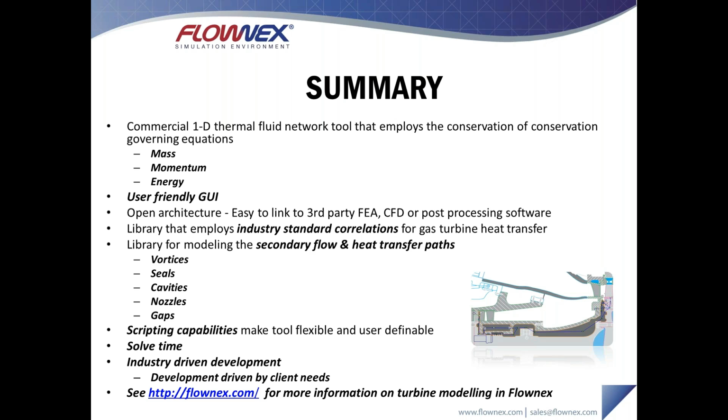The software itself has scripting capabilities to allow users to input custom correlations. So if you have in-house correlations that are not publicly available, these correlations can quite easily be included in your model in a simple C# script. It's very easy to use and has minimal overhead code. The script can then be linked to pressure drop components or to heat transfer components to specify custom friction factors or custom pressure drops inside of your system, or heat transfer coefficients, for example.